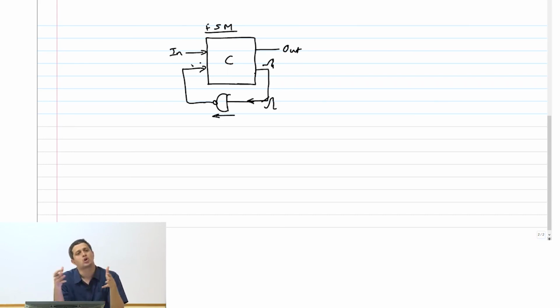Question is, can I just put logic gates like that and make it work? Technically it is possible. Point is that the delay through these logic gates is now a fixed number. So if I have to run it at a different frequency, then I can't do much.